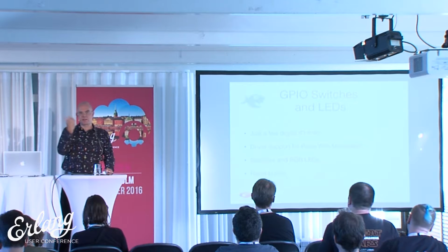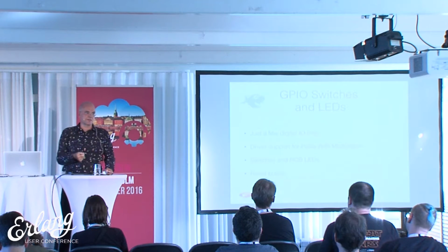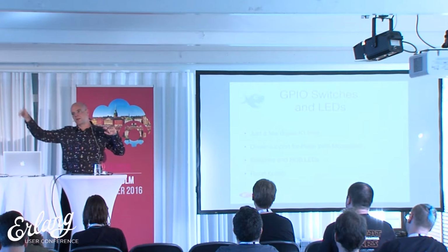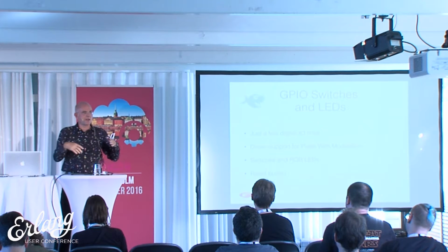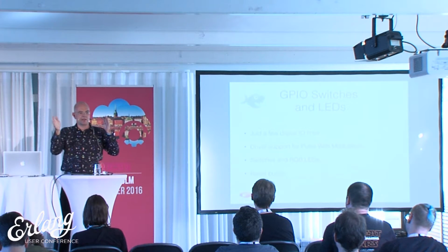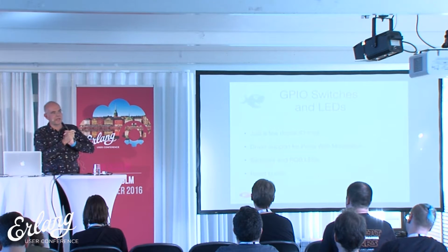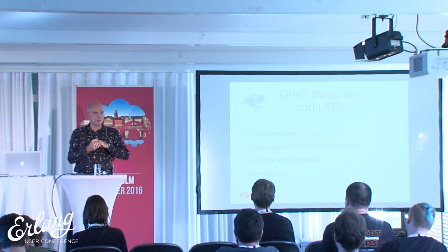These bits in the register we will make accessible by some Erlang calls, with which you can switch the bits on and off or set them all at once, or also have some driver support to do pulse width modulation, so basically a rectangular wave where you send a value to the driver, and it then makes the on time longer or shorter, which you can, for example, use for the LEDs, which are also connected to a kind of GPIO.